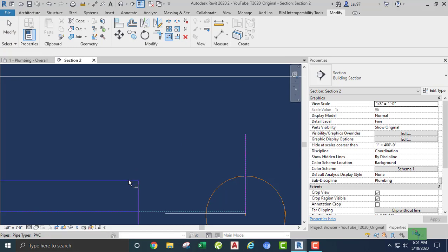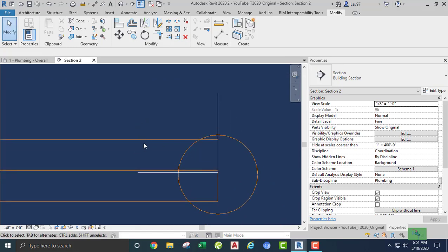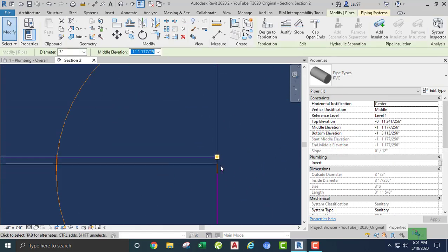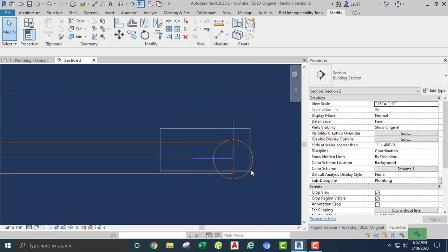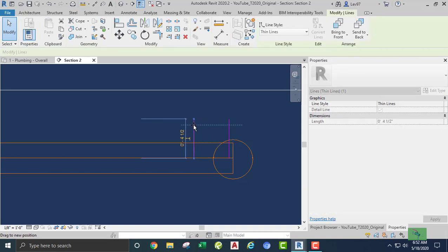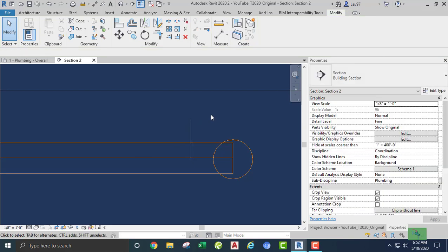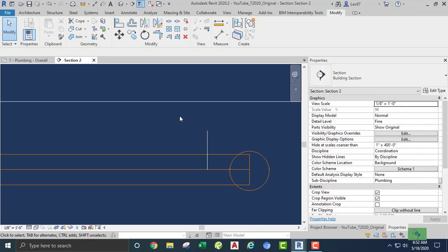and extend one pipe, okay. And what I'm going to do is align my pipe center line with the existing pipe center line. That usually works. I can try and eyeball the two center lines, but I get that right maybe 10% of the time, maybe 20% of the time. And this usually works about 80% of the time, 90% of the time.